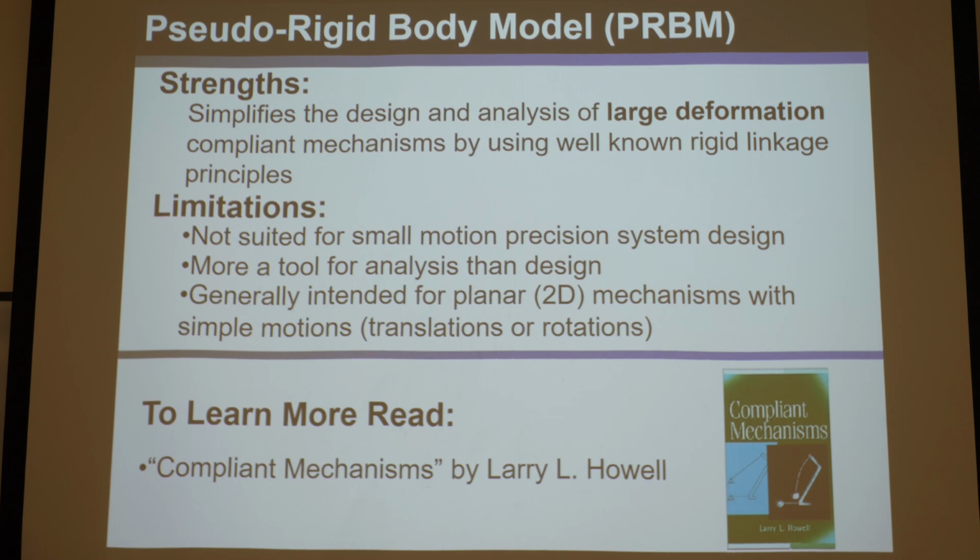So there's value in pursuing all these approaches because you can compare and see if you found a design that's the best. By the way, going back to topology optimization and pseudo-rigid body model, you can't ever know if you found the best design. In topology optimization, things optimize to the nearest local minima. Over the full design space, the goal would be to find the global minima, the point where the objective function minimizes or maximizes, depending on how you set it up, right? But finds the global, the best over the full design space. You can never know if you found that.